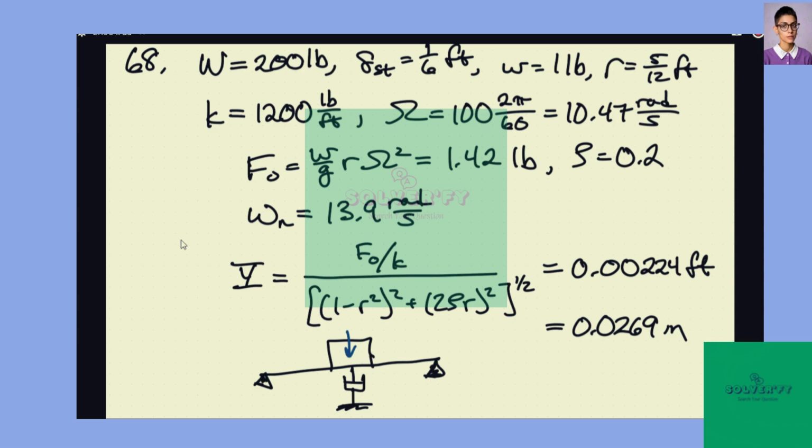So we have, again, because of this, the beam acts as our spring, and then we have this damper down here that will dissipate mechanical energy. And then I think it's running an eccentric flywheel, so we have a rotating unbalance for our amplitude of our forcing. We're told that the motor weighs 200 pounds, and the static deflection of this beam, when you put the motor on it, is 2 inches.